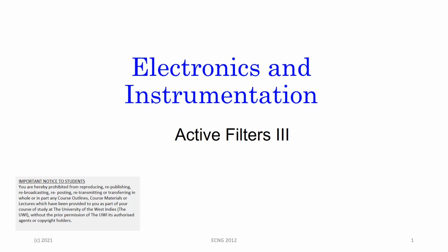then the transfer function simplified into two fairly straightforward forms that you could remember. And one in particular was very close to something that we discussed in the signals and systems class, so you could remember that form. And remember that the high pass filters always have an S squared in the numerator. In other words, the low pass filters of the types that we've designed only have poles, but the high pass filters have zeros and poles in them. If it's a second order filter, it means you have two poles and two zeros for the high pass filter. If it's a first order filter, you have one pole for the low pass and one pole and one zero for the high pass.